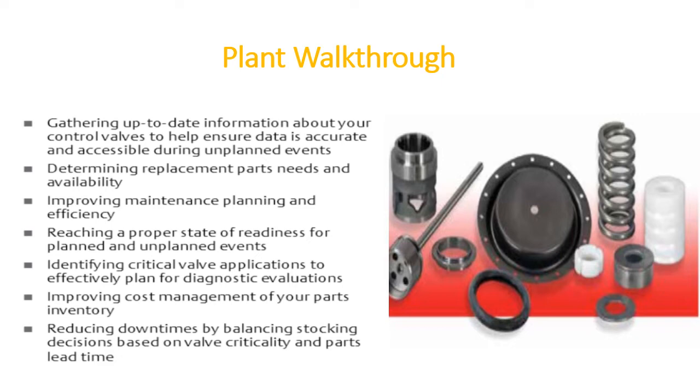Hard part replacement is required for only around 20% of the valves. For the remaining 80% of the valves you need to replace the soft parts. That means the gasket, the seat, the o-ring, and the packing parts need replacement.